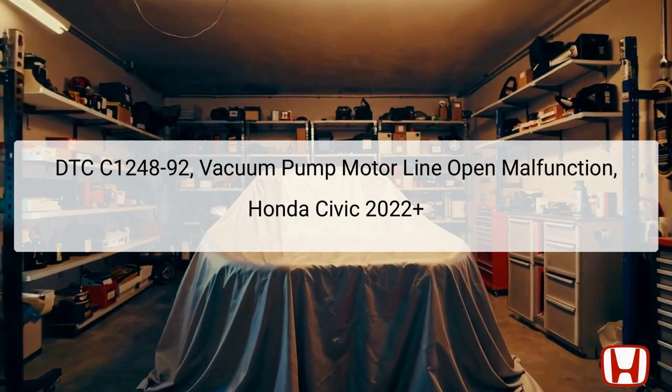The focus of this presentation is on the Diagnostic Trouble Code DTC C1248-92, recognized as a vacuum pump motor line open malfunction in the Honda Civic models from 2022 and onwards. This code indicates a malfunction in the vacuum pump system, essential for functions such as brake assist. Specifically, when the electric vacuum pump's lines show abnormal conditions, the control unit triggers this DTC to alert the technician of potential issues in the electrical circuitry.